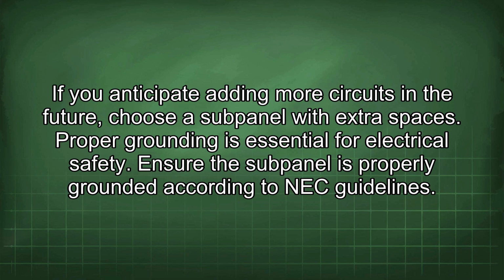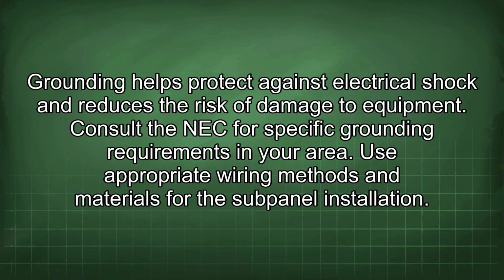Proper grounding is essential for electrical safety. Ensure the subpanel is properly grounded according to NEC guidelines. Grounding helps protect against electrical shock and reduces the risk of damage to equipment. Consult the NEC for specific grounding requirements in your area.